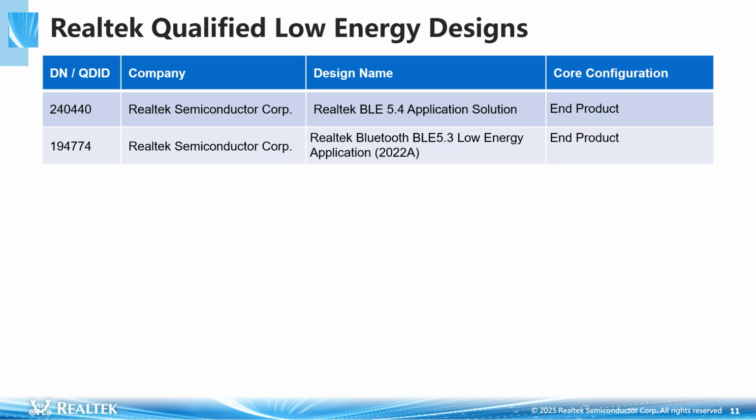If your product does not fit into the above categories, you could use the Realtek BLE 5.4 application solution QDID 240440. Customize your solution according to the actual functions of your product. Complete the necessary tests as required by SIG, submit the evidence, and achieve final certification.